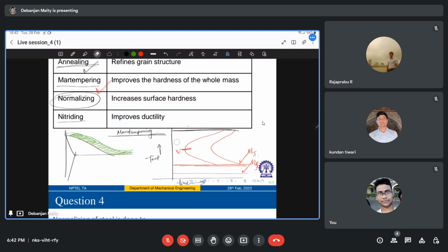So let's say this is your martensitic start range, right? What you do is you go up to here, a little above the martensitic start temperature of the steel being treated, and the component is soaked in the bath until the temperature is uniform throughout.